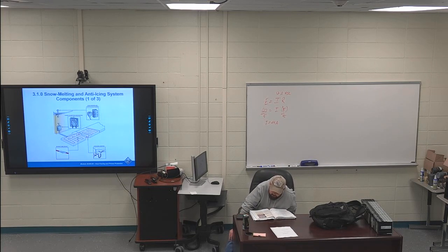321, installation of heating cable and components. I've got that first paragraph, last 2 sentences. It's about the second half of the paragraph. The minimum amount of heat cable required can be calculated using the following formula. Typically, 3 feet of additional cable should be allowed for making power connections. That's what you want to key in on. Whereas with your heat tracing, 2 feet were used for splices and tees and stuff like that.